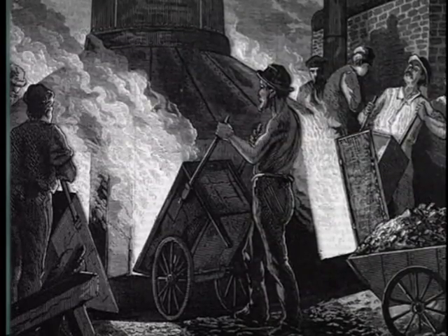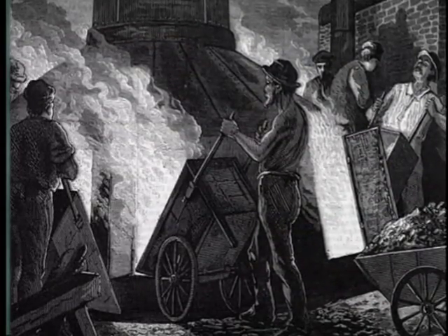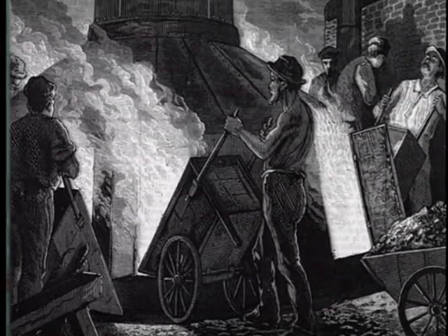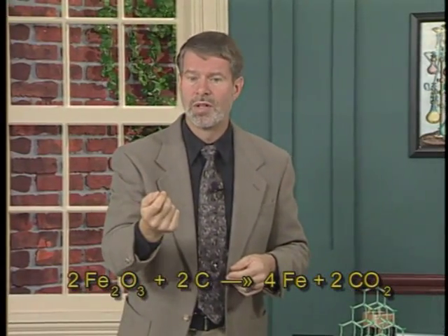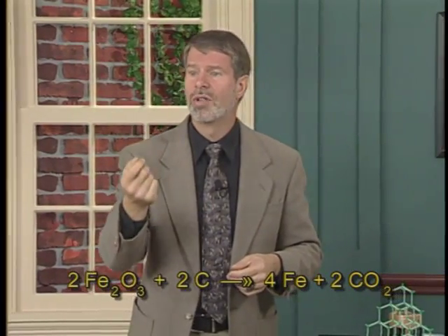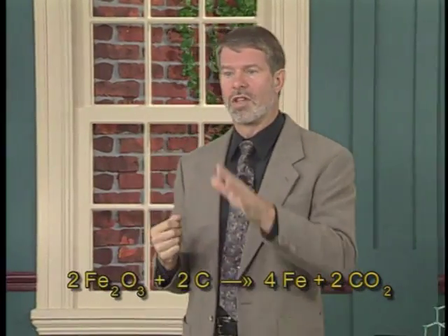So you take iron oxide ores, and they used to be smelted in a fire by mixing the ore with lime, that's calcium oxide, and hot burning charcoal in a furnace. So a typical reaction is iron oxide plus carbon goes to iron metal plus CO2. And the lime, that calcium oxide, serves as a flux which lowers the melting temperature of the ore and thus speeds the reaction. This process has been used for thousands of years to make iron.